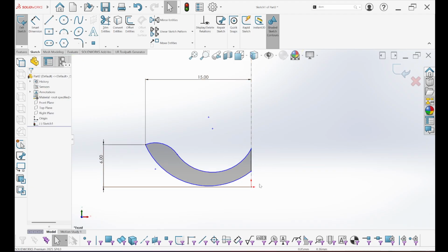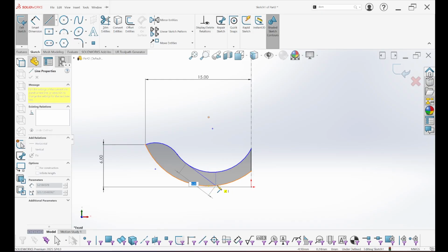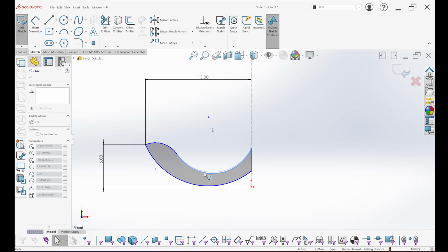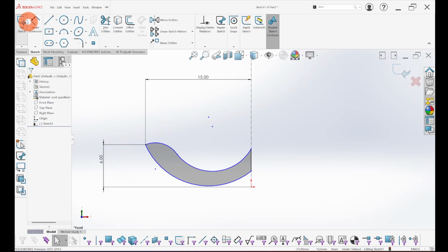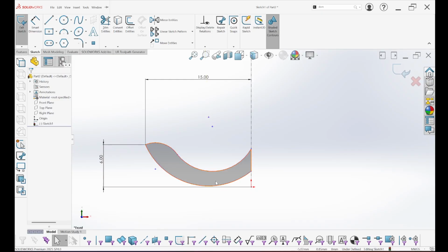Here you can sketch the shape you want. Just be careful not to make it too small. For example, this is 5 mm thick. It's good. It's a bit thick actually, but it's better to have something a bit thicker than not enough. Actually, that's not possible, what you just told me. No, voilà. This is 2 mm, because if this is 6, this cannot be 5. So this is 2 mm on 6. Don't do less than that in terms of thickness of plastic.